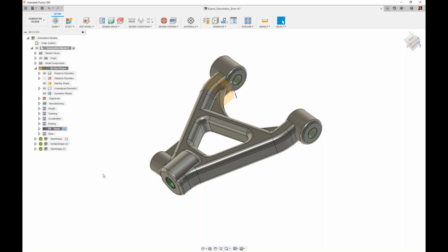There's a question on, is it Nastran under Inventor? I'm not sure if there was more to that question, but when you promote the outcome back to Fusion, you get to leverage the tool within Fusion simulation, which will leverage all the setup parameters you've already done within the generative workspace. In theory, you could take that part to Inventor and use Inventor Nastran if you wanted, but you would not have the benefit of the load cases being transferred automatically.